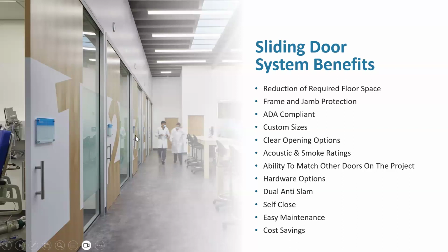This is a project we're proud of up in the Pacific Northwest. This picture's here for a reason. Another thing you want to be aware of is the weights of these doors. So this is actually a 10-foot tall door, and how you achieve that. There are some weights we can get into, well, per project, that the soft close might overwhelm, but you could do a foam core to keep the weight of that door lighter. And that's what we did here.